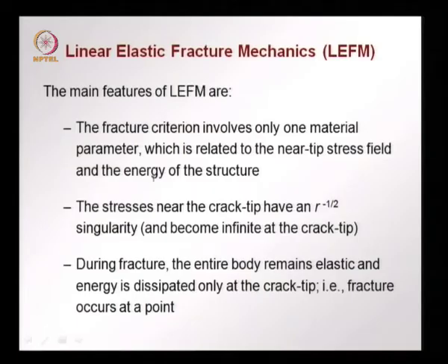Until now what we have discussed is called linear elastic fracture mechanics or LEFM. The main features to summarize are that the fracture criterion involves only one material parameter, which is related to the near tip stress field and the energy of the structure. The stresses near the crack tip have an r to the power of minus 1/2 singularity and become infinite at the crack tip.